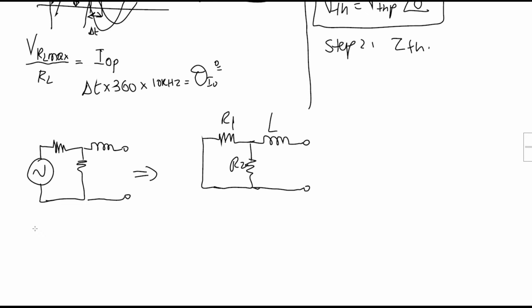Now, if we were given a resistor and were asked to find its value without using the color coding technique, or without using a multimeter or ohmmeter, the only way is to supply it, because Ohm's law says V equals Ri, so R will be V over I. To find the value of R, we should have a V across that resistor, and the current flowing through it.